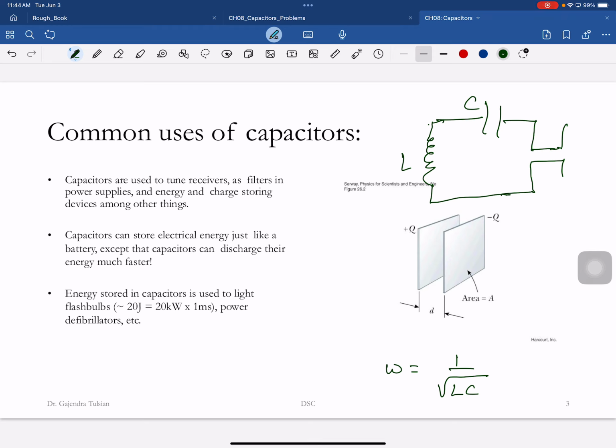How do you pick out the ones that you want to listen to? Classically you'd have a mechanical wheel that changes, I guess, the inductor. Yeah, you're either changing an inductor or a capacitance. So let's say you want to pick up 89.9 megahertz.